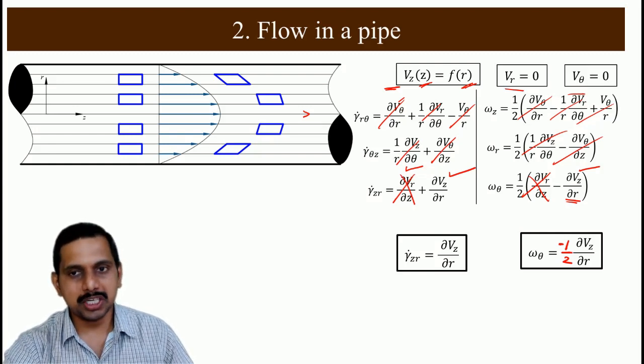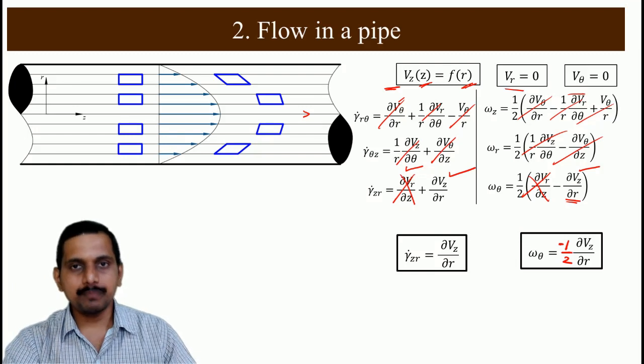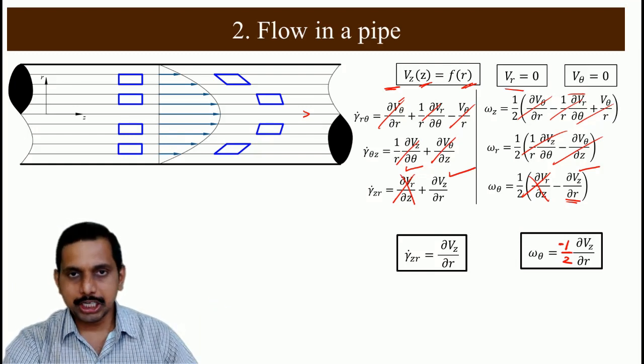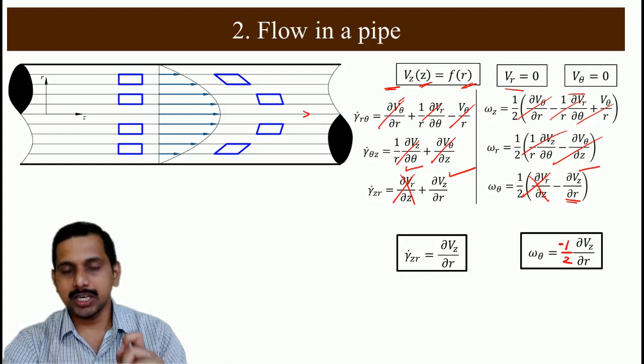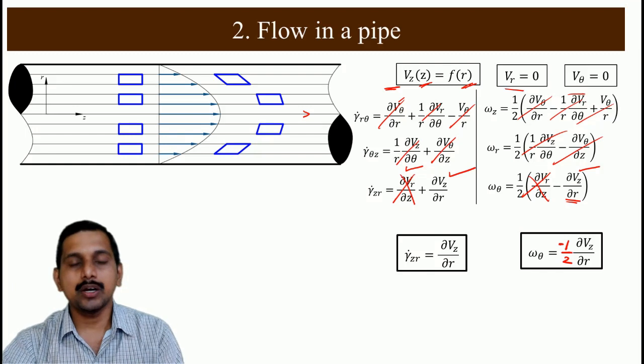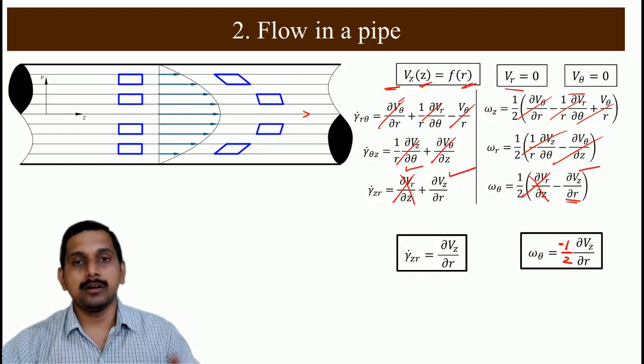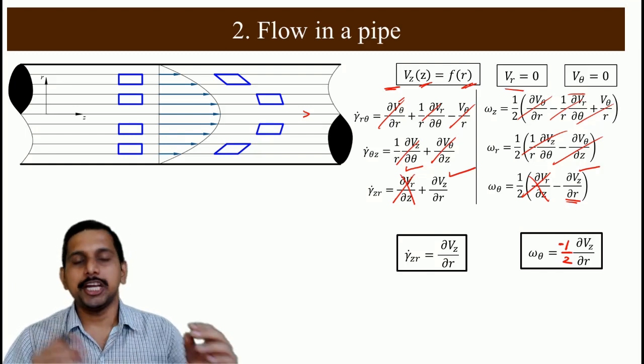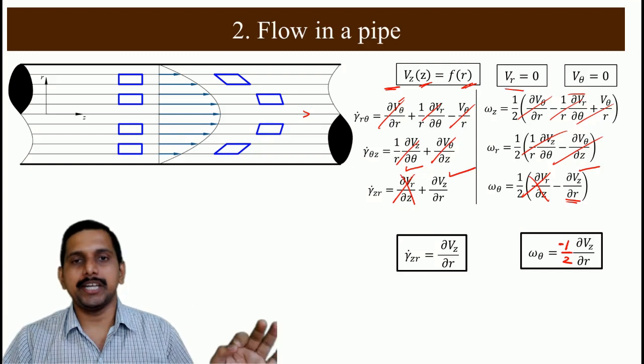This is the rotation rate. So this is a flow where both rotation as well as shear is there. Rotation, here one of the things we have to understand, rotation does not mean that the whole fluid mass should be rotating. It means each fluid particle should rotate.